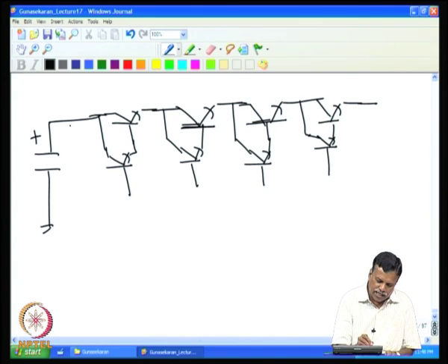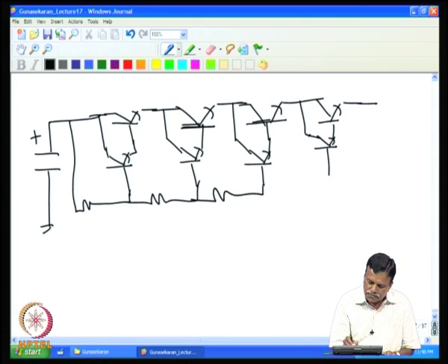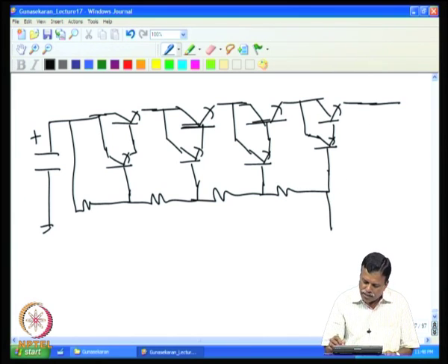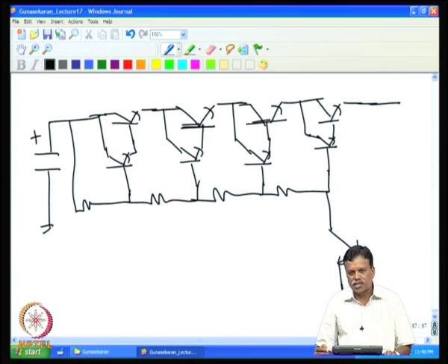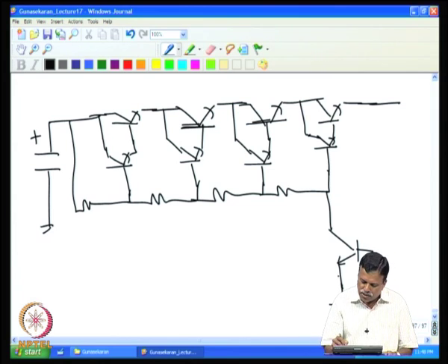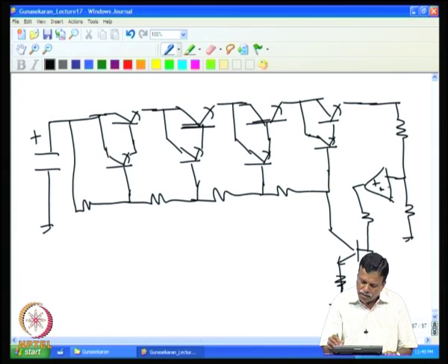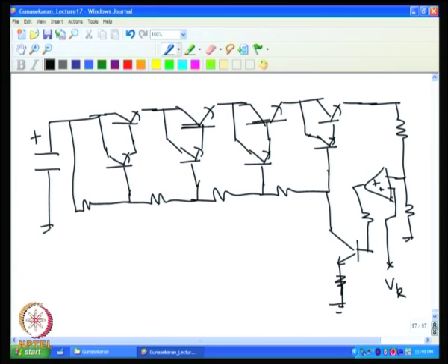So, now I can add resistances of equal values. Then, for example, in this case our regulator transistor can be this. If necessary, this also can be made parallel. Right now, I will not look into it, because this is only low power, and 1000 volt low power transistors are available, it is not a problem. So, this can be connected to the error amplifier, and the output we can connect to this, and the minus input is connected to V reference. So, that actually becomes V output.